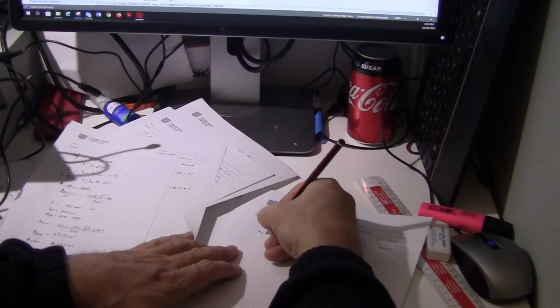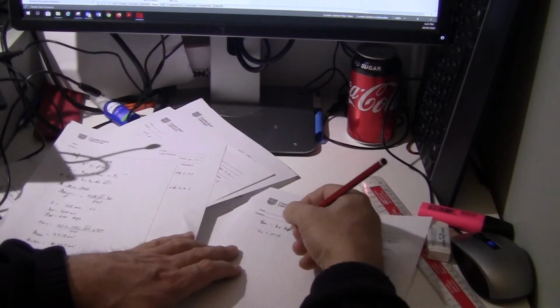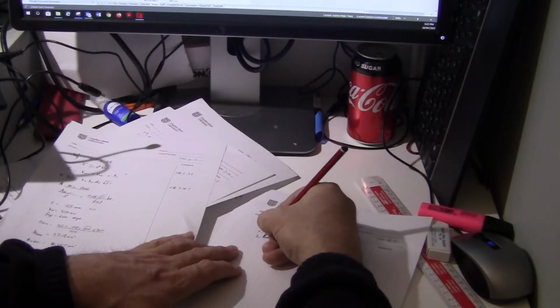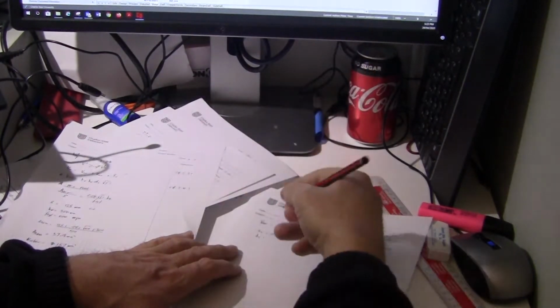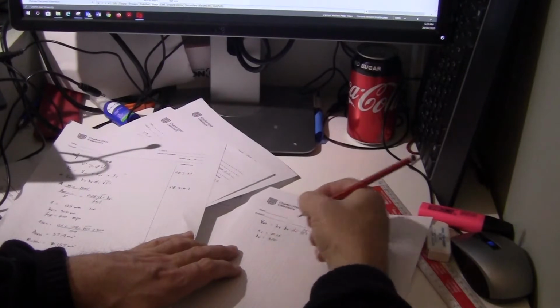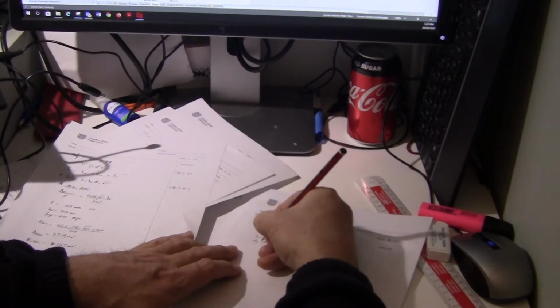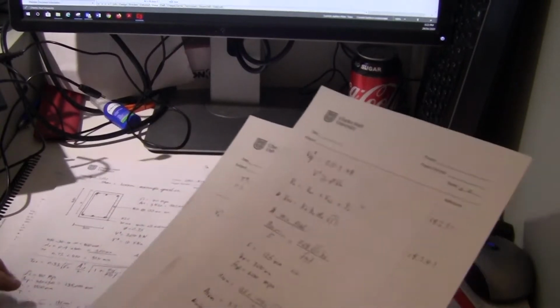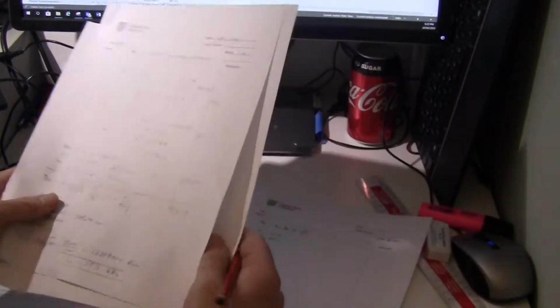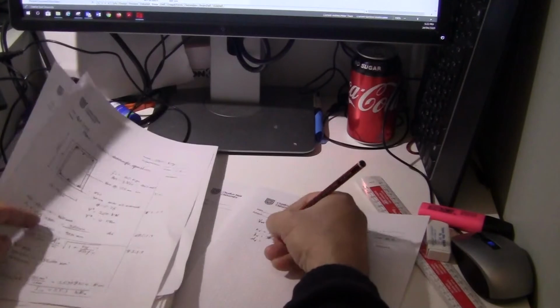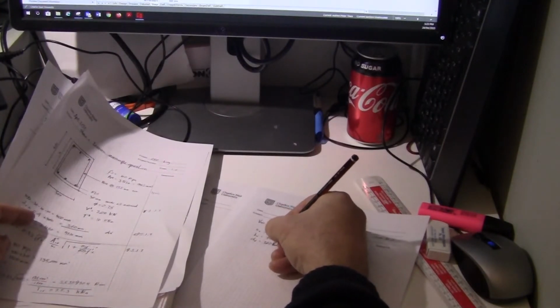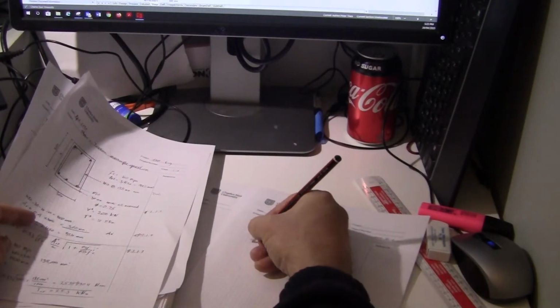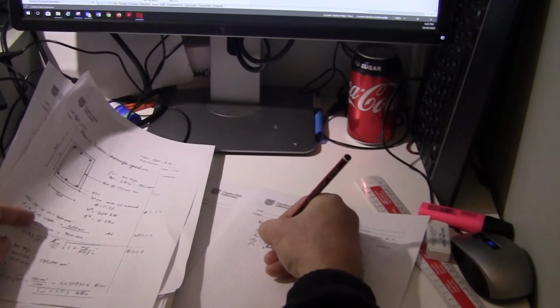So KV equals 0.15. We've just found that. BV is the bottom width of our beam, 300 millimeters. DV is that shear depth. You recall we worked that out quite a while back. That was on the first page here. That is 360 millimeters. And our F-C, of course, is 40 MPa.